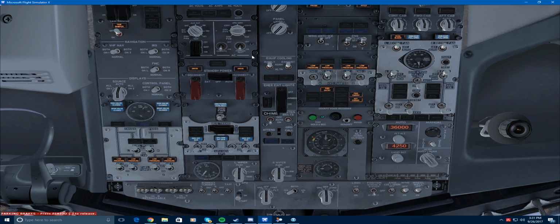Okay. Next, I'm going to turn on my hydraulic pumps, so that the control surfaces can get ready to be used. And once my hydraulic pumps are on, I'm going to press this switch here, which is the yaw damper. What that does is make it so that the yaw is always centered unless there's a direct input from the captain. This will prevent the aircraft mid-flight from losing control because of bad rudder input. So you're going to put that in. And this relies on the hydraulic pressure to be on. Okay.